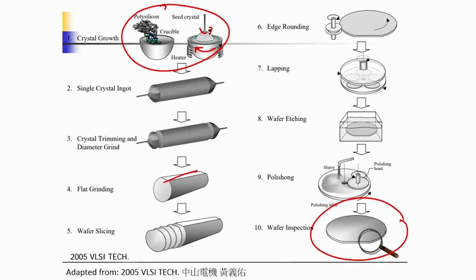So, what is this particular flat? If you see in my hand, I am holding a silicon wafer. Can you see this flat here? This is a flat. The wafer is round, but there is a flat here. This is the primary flat, and all the wafers would have a primary flat. So, this is one wafer. Let me use another wafer. Another wafer is right over here. Let me show it to you.